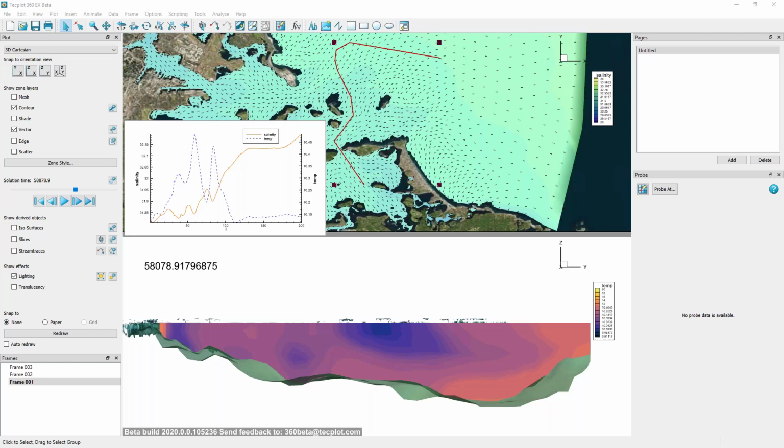And then there was another one. Can I use an imported Google Earth image as a georeferenced image? The answer is maybe. Certainly, Tecplot can import any image into the plot. So it's one of, do you have an accompanying world file? Or in this case, Jared showed a PGW file. So that's a PNG world file. So you need that world file associated with it, which defines the region of that image. If you don't have a world file, you can just bring it in as an image and then pan and zoom that image to get it to line up with your data.